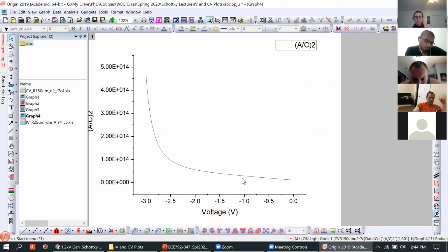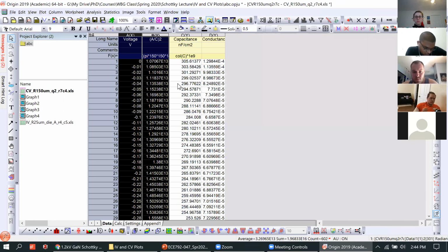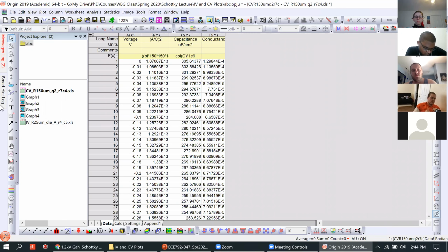Instead of a straight line, previously I was plotting only till 1, 0 to -1, and now if you go higher, I see different doping, meaning either I have a different doping in my device actually, or maybe I have some traps coming into the picture. So yeah, that's what I wanted to show, how to normalize all of this, and when you get data, to make sure you remove unnecessary things and you only plot what is important.